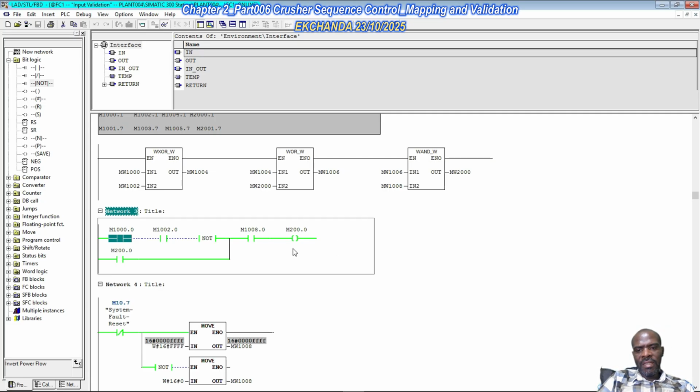the system is okay. You tripped out on account of a fault which was basically just due to a loose wire, and then the system stops, the wire gets into position, and you are not able to pinpoint the exact fault location, which is why we're saying those transitions in the protection inputs should not self-reset.